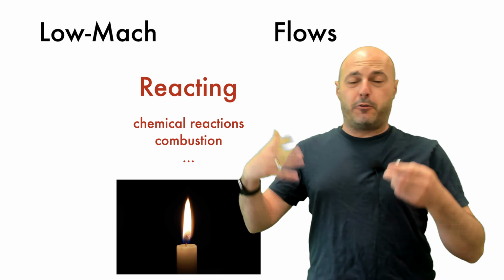Pretty much all atmospheric flows are low Mach. The Boussinesq approximation that you've probably heard of, that is fairly used in atmospheric flows, is a special case of a low Mach condition. Sometimes supernovas in the universe, flares, fires, open fires like forest fires. All of these things can be modeled as low Mach flows, and they are low Mach flows.